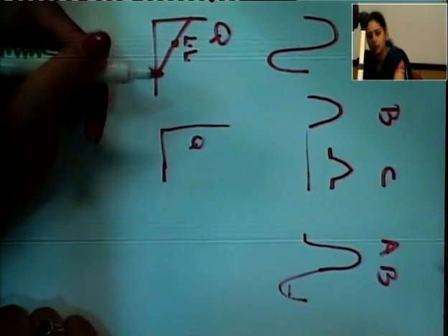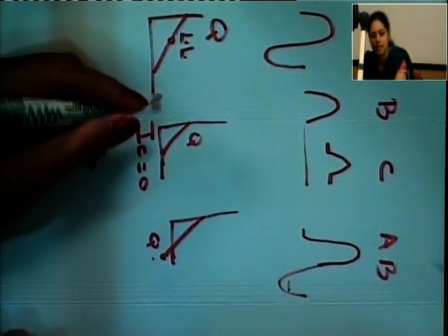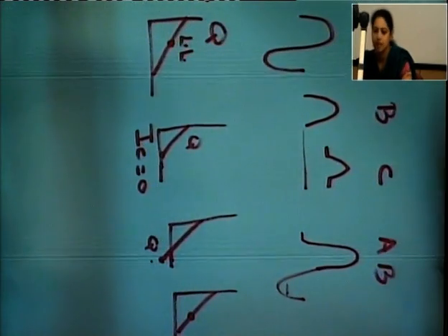is different. You are placing your Q point at the cutoff voltage, that's why your IC is equal to 0. For class C amplifiers, it is beyond your cutoff voltage. So some kind of reverse bias is provided in case of your class C amplifiers. In class AB amplifiers, this Q point is shifted near the cutoff voltage. These are the two main differences by which you can differentiate between these types of power amplifiers.